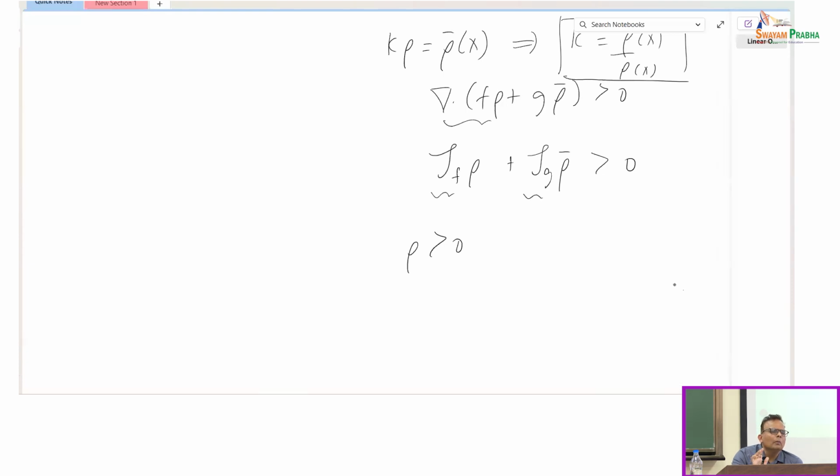When we constructed a cost function, you have some state cost and some cost on the control, and you're interested in minimizing that state cost plus the control cost, starting from each and every initial condition. Given an initial condition where I start the system, I'm interested in finding a trajectory such that the cost is minimized starting from that initial condition.